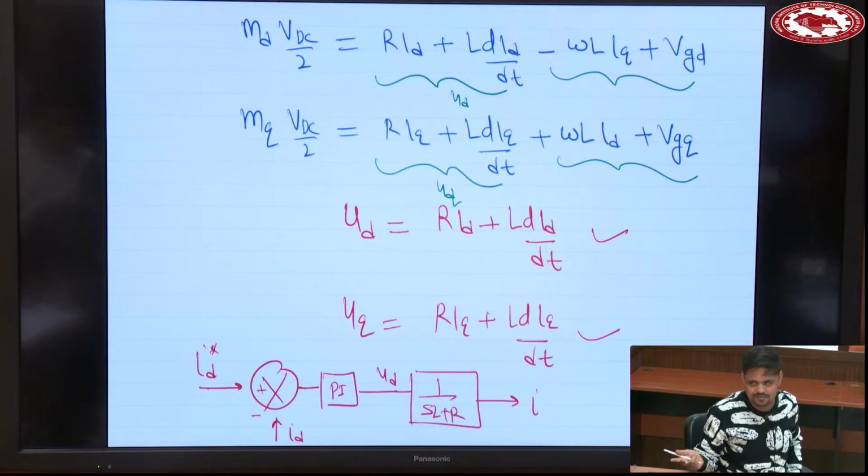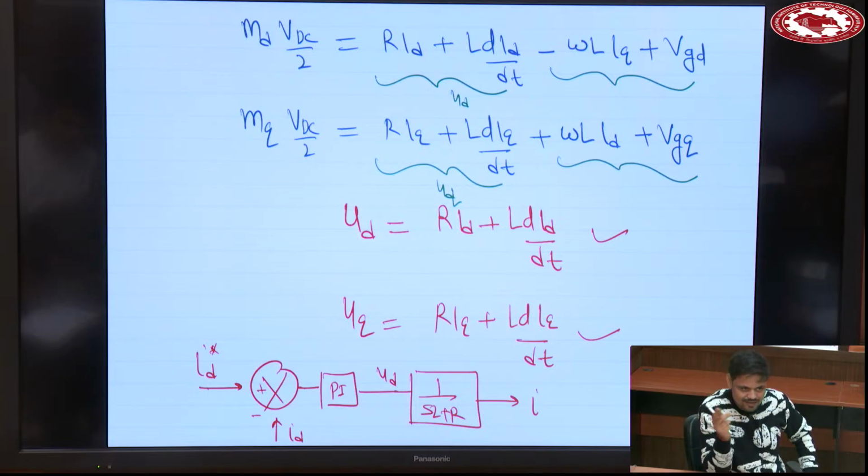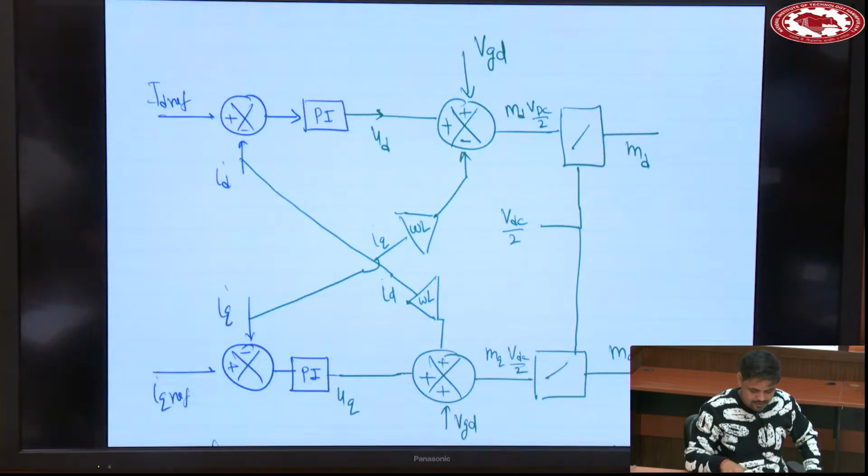Since you are dealing with the average model, you can take tau as 1 millisecond or so. Otherwise, sir told it another way today, but the objective was the same. He was saying it should be 4 to 5 times something like that. The time constant should not be so fast that it crosses the switching frequency also. It should be limited to at least 2-3 times lower than the switching frequency. Otherwise operation will be unbalanced, uncontrolled.